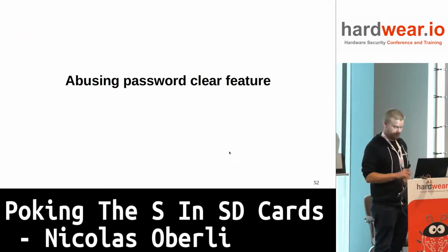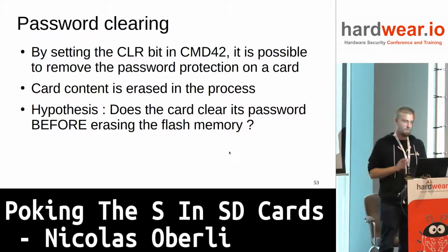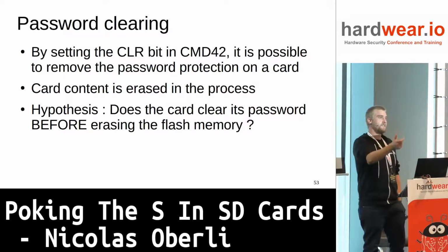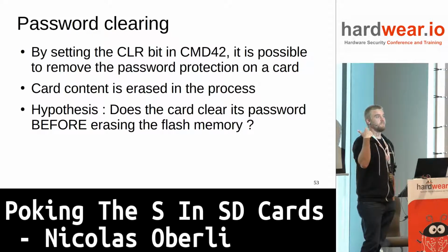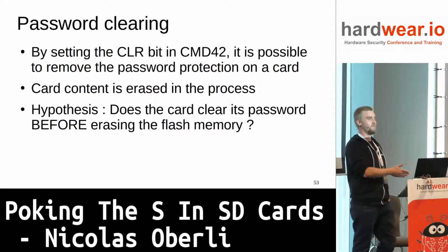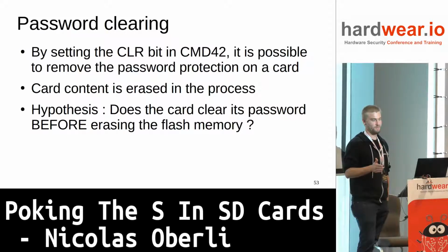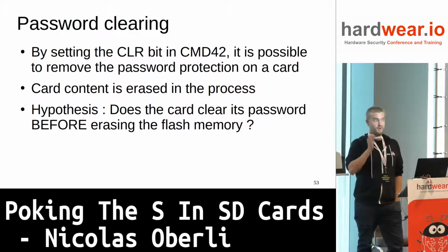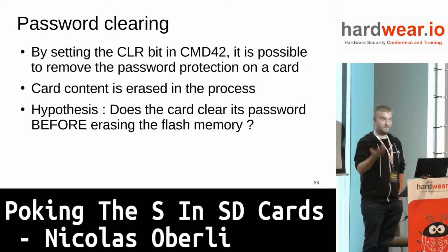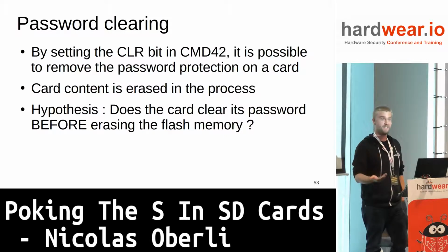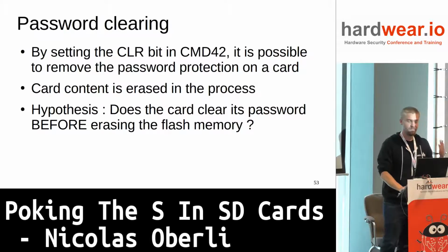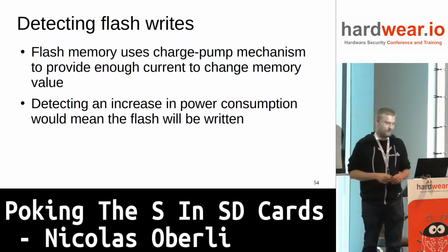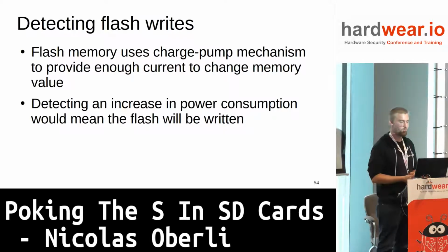That's cool. But there's one different thing that I also wanted to check: when you send this clear password command, what is the card doing first? First erasing the data or first removing the password? Because if it's removing the password first, that means that if I remove the card at the right moment, I'm able to get a card with no password protection anymore, but still the data inside. Sounds like a good idea, but how do I do it? I mean, it's not that easy to, let's say, press enter, then pull out the card. There's another way to do it.